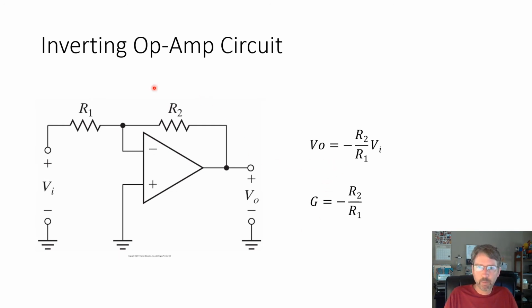So once you recognize this circuit, when you see this configuration, you know it's the inverting op amp, so you don't have to analyze it. But don't assume, make sure you're looking at the right circuit, because there are lots of different circuits.